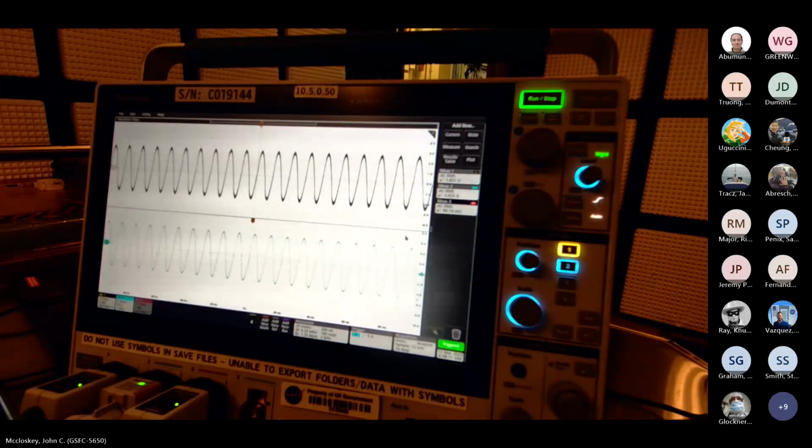So the point there is that whether you're doing this by hand or especially if you're doing it in a control loop, you want to drop the level before you jump to the next frequency. Okay, and you can set it to minus 6 dB, minus 12 dB. Minus 12 dB is generally enough.